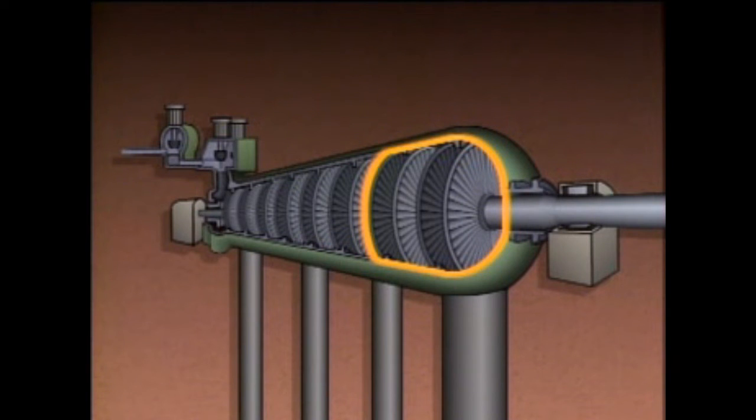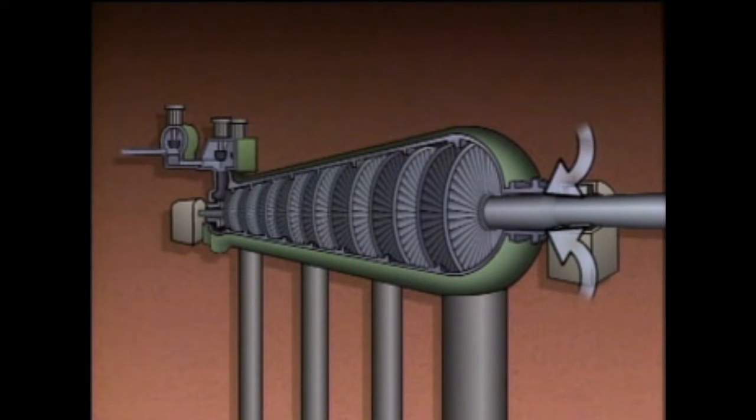In the turbine stages in which pressure is less than atmospheric pressure, air will try to leak into the turbine. This reduces turbine efficiency because the air must be removed in order to maintain the vacuum. Air leaking in also can cause a thermal stress problem in the turbine. The outside air can be much cooler than the inside of the turbine, and when cool air gets into the turbine, drastic temperature changes occur. The resulting thermal stress on turbine parts could cause them to crack.